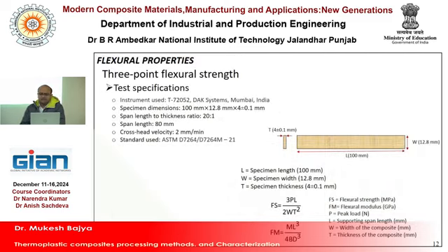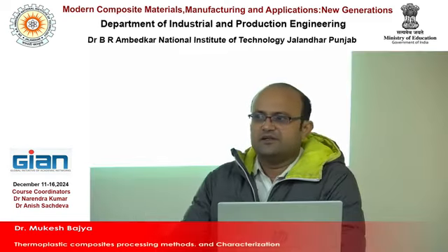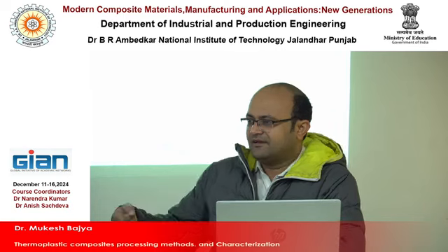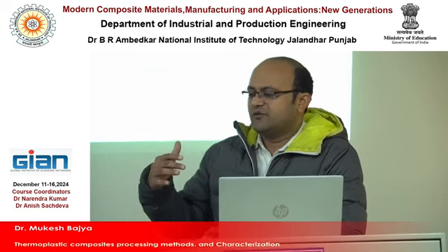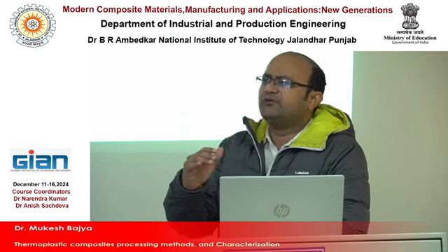Then the flexural rigidity of the composites. This is the ASTM D7264 standard. As per the standard, you need to prepare the composite, and you can calculate the flexural properties of the composite, because generally people also test the tensile properties. But suppose I am using a composite to manufacture this table, in that case generally the load is on the cantilever principle, not like a tensile load. If you are talking about impact, then you will go for the impact test, for example if you have used the composite in the bonded preparation of an automobile. In that case impact is an important factor. So as per the requirement, you need to plan the test.